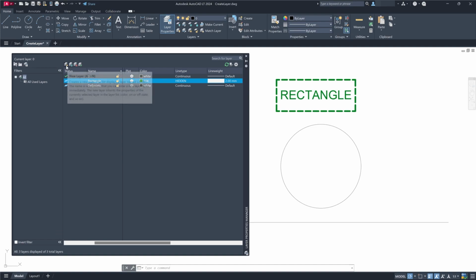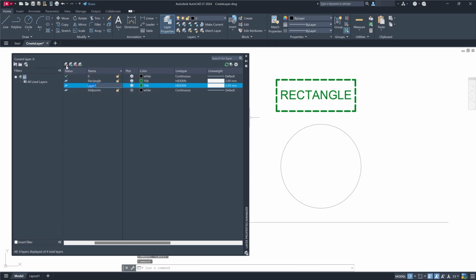So we'll go back to our new layer and select that. Now, because I had my rectangle layer selected, it took on all those properties. It created a new layer with all the same properties. You can do that if you have something else in there that needs those same properties, or if you're just going to change one out of the 3 properties, or just whatever you needed to do. This is a slightly quicker way than just creating a whole one from scratch. So I'm going to label this one my circle, and now I'm going to put the circle onto my circle layer.